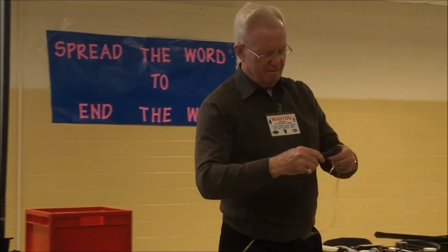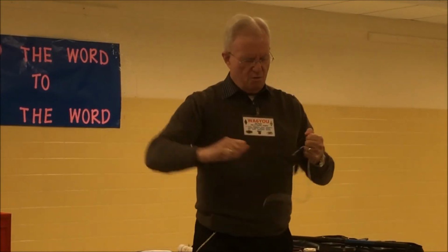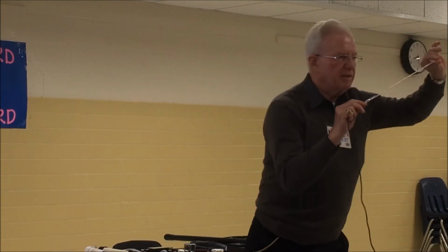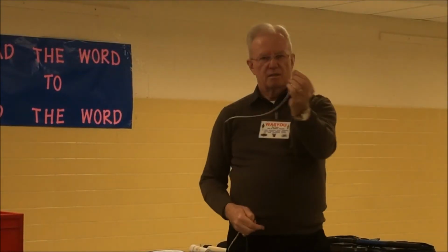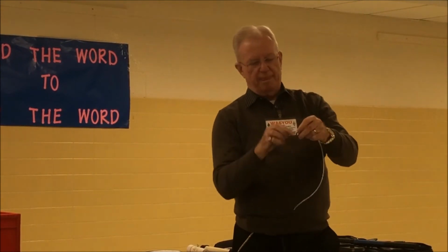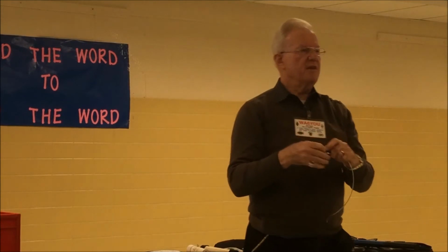No insulators. This works quite well, by the way. This is Dacron. So if you're ever really in a hurry to put up an antenna, you take the end of your dipole, make believe that's the end of my dipole coming out of the tree, and you make a little twist here, and you tie. All of us in the Navy know how to tie these knots, right, Mike?